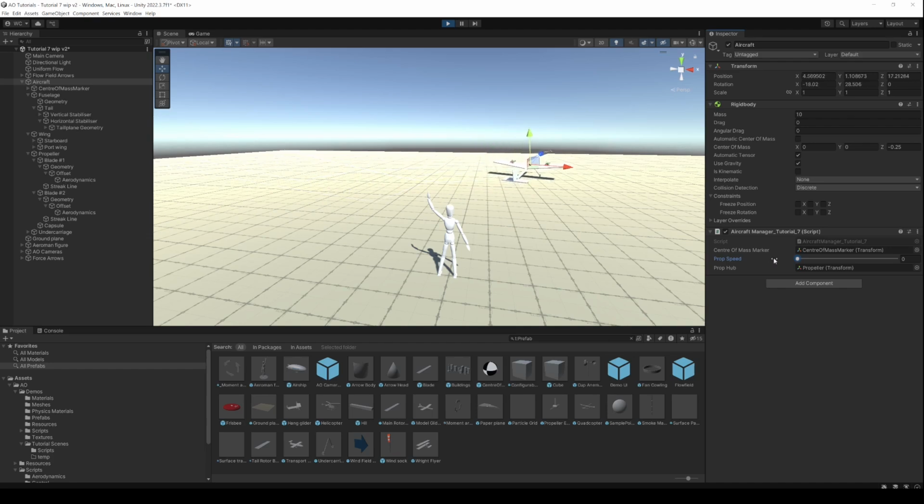Okay, we got it back on the ground too. So that was interesting. So when it took off, it pulled to one side, and that's not because the fin is actually on straight. The reason is you get a torque from the propeller, and so the drag on the blades, a bit like the drag on the wing, is actually trying to slow the propeller down, but that is acting as a torque effectively on our propeller hub, and that's causing the aircraft to twist in the other direction, and that's what causes it to turn.